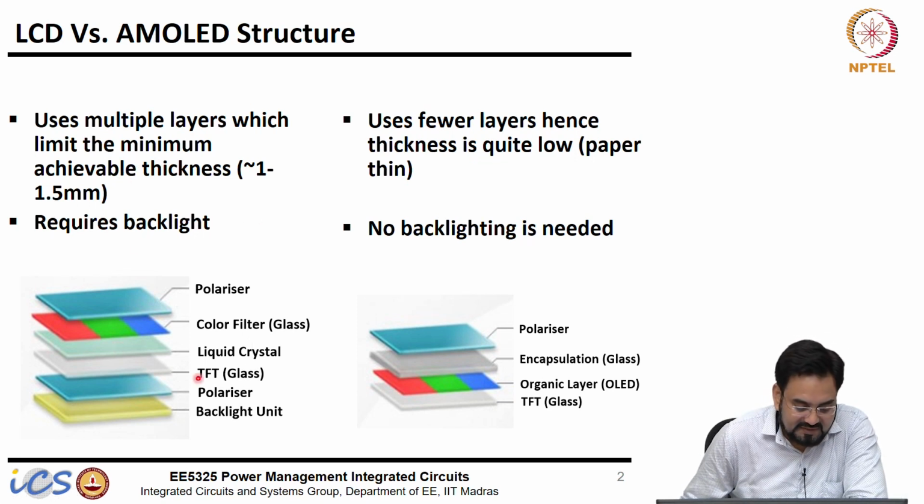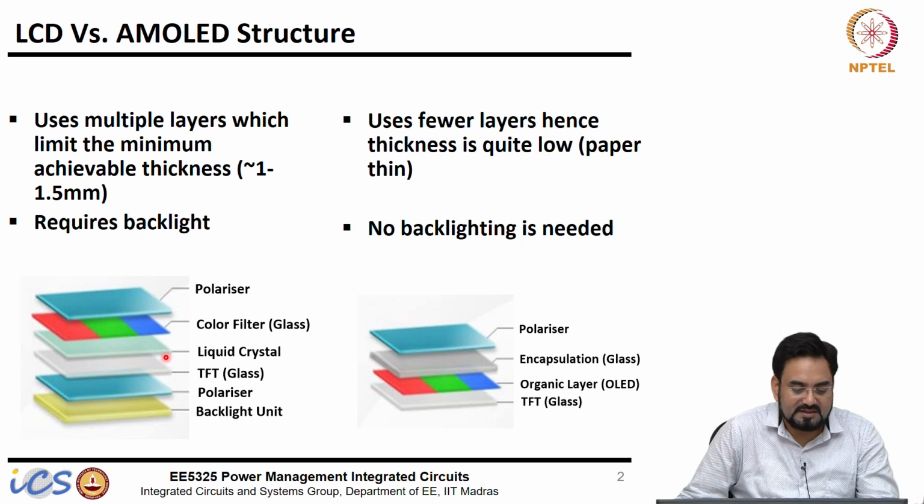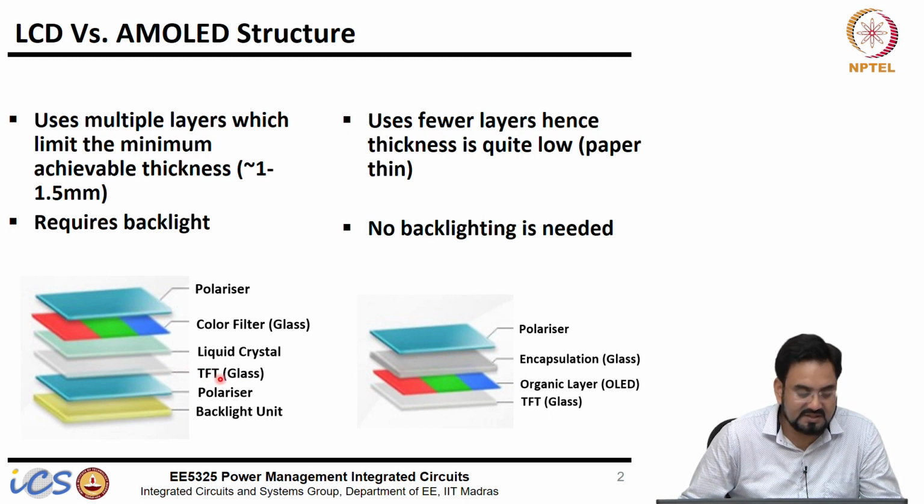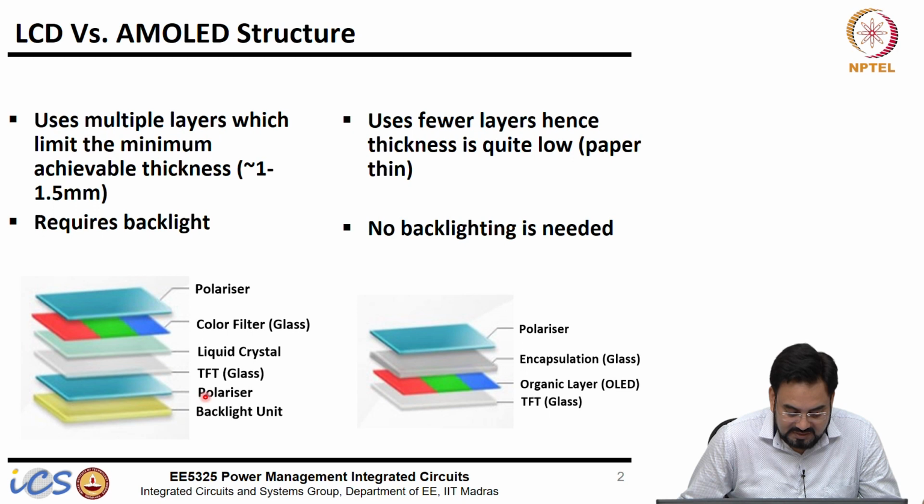In case of LCD, the left hand side is showing the different layers of your LCD display. It is not just liquid crystal, but this liquid crystal is sandwiched between many layers. You can see here it has a polarizer, a color filter which is nothing but glass. Then your liquid crystal comes, then you have a TFT, which is again glass; TFT is your thin film transistor. Then you have a polarizer, put on both sides, and then you have the backlight unit, which is nothing but white LED. So you can see there are so many layers here.